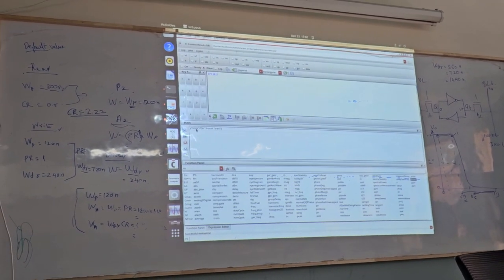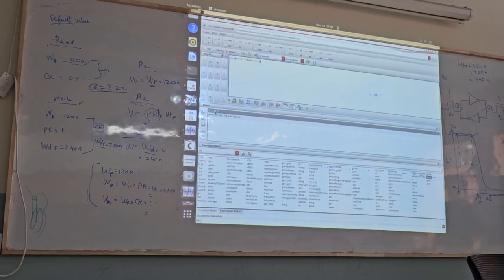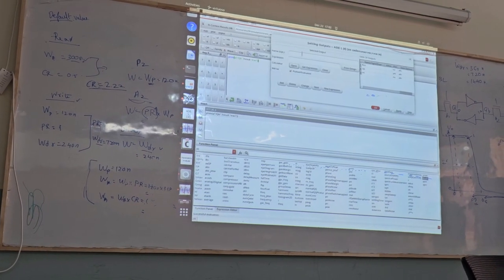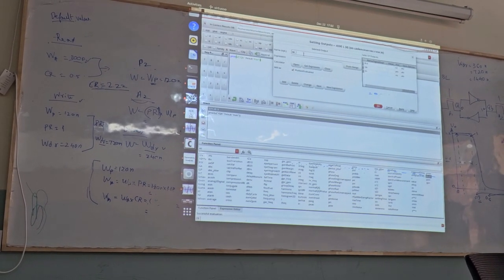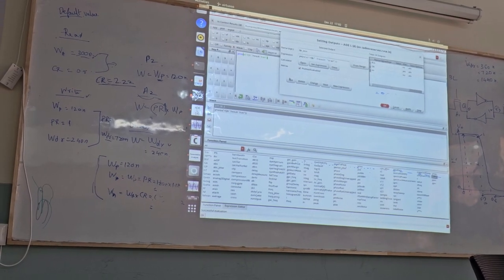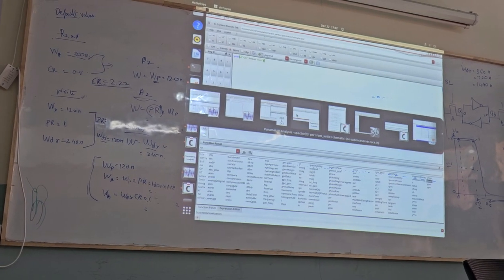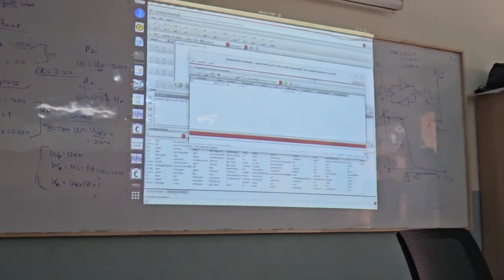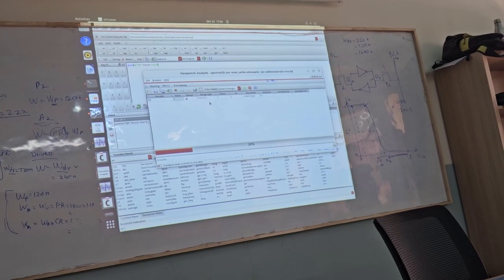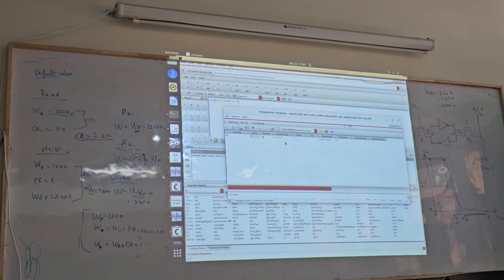But to define an output expression, I need an expression to be there in the buffer. So double click on the stack expression so that it gets copied onto the buffer. Now you can switch back to this output setup. Probably you might have to redefine this. Click on get expression, click on add, click OK. So now what I do next is to perform the parametric analysis only on the PR with a final step size of 0.1. And when we do so, we can find the PR ratio.